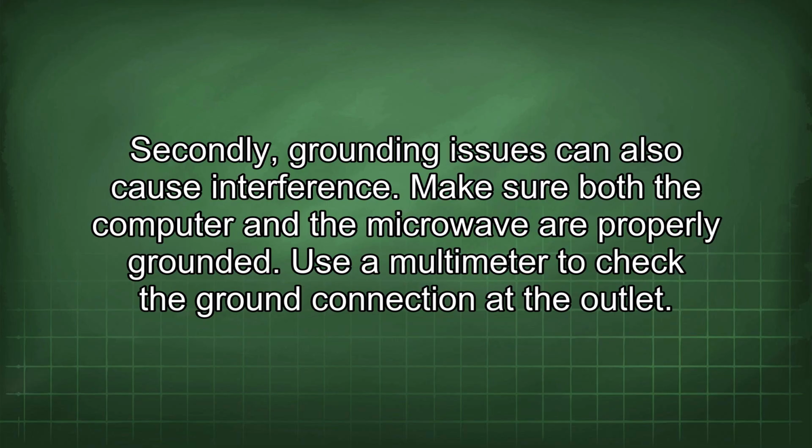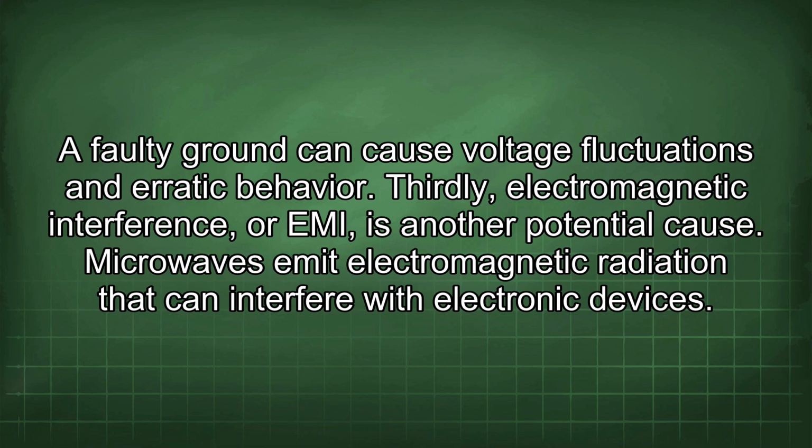Secondly, grounding issues can also cause interference. Make sure both the computer and the microwave are properly grounded. Use a multimeter to check the ground connection at the outlet. A faulty ground can cause voltage fluctuations and erratic behavior.